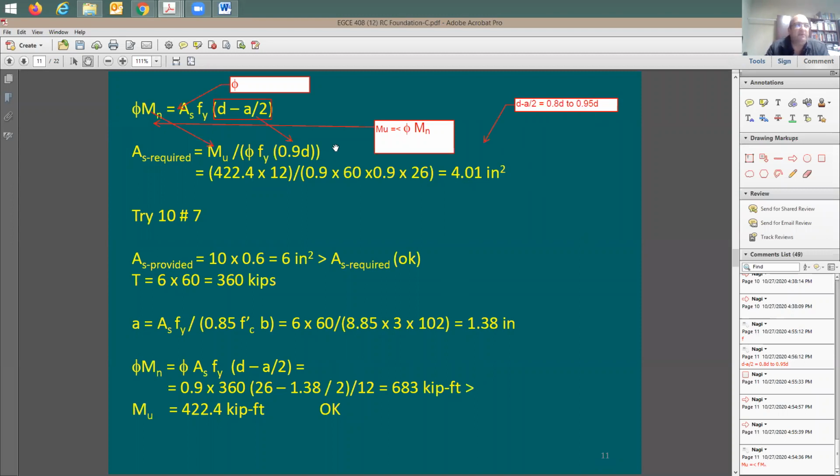Now in your analysis, if you decide here to use 85%, I cannot say this is wrong, right? It's just an assumption to come up with the amount of reinforcing. But it's very standard that we assume it's going to be 90% of d, and this is very common between structural engineers. Now I can run the numbers here and see how much is the AS required.